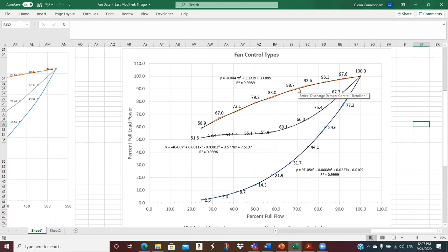But you've got a measured power, so you know what that is. You could divide that by 0.9, and that would give you a projected 100% power. Or you could take the capacity of the motor to get your 100% power. At full load, that fan is probably going to pull pretty close to 125 horsepower, if that's the size motor that's on it.